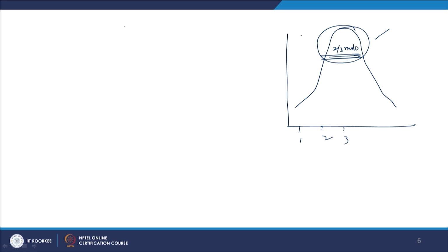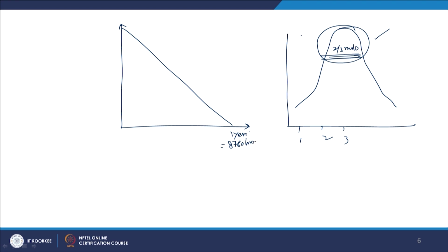But it is not depicted normally in a power plant. When we depict the data, it is always a cumulative frequency, okay, for 1 year. How many hours are there in 1 year? 8760 hours, right. So, we go by cumulative frequency, and now we can say for example, this is the base load, this is kilowatt. So, area will give you the new unit, kilowatt hours. So, this is the base load and this is the peak load.